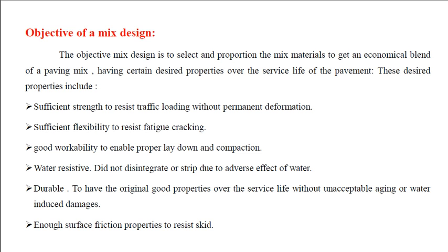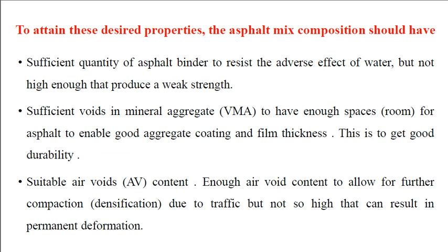Then, good workability in order to enable proper laydown and compaction of the pavement mix. Water resistance. Then, durability in order to have the original good properties over the service life without unacceptable aging or water induced damages. And then, enough surface friction properties to resist the skid of the vehicles.